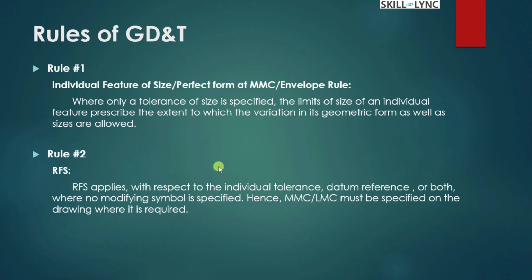So these rules, hard and fast, override the GD&T tolerance zone we are providing. It means that unless we override this using modifiers, whatever feature of size we are machining will pertain to the perfect form size without any undulation, whether in the maximum material condition or in the regardless of feature size condition. So we always need to consider the manufacturing processes we have in hand and use these modifiers diligently to ensure that the form, fit and function of the feature get satisfied.